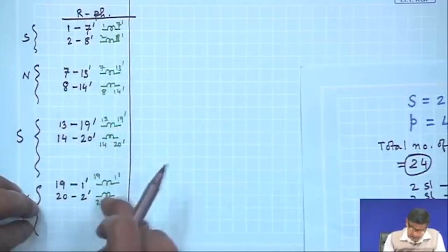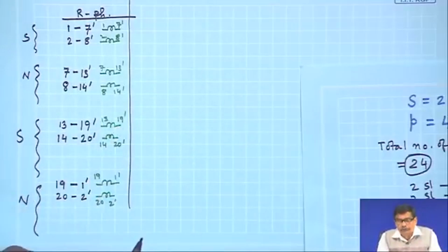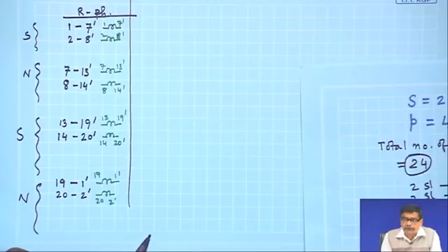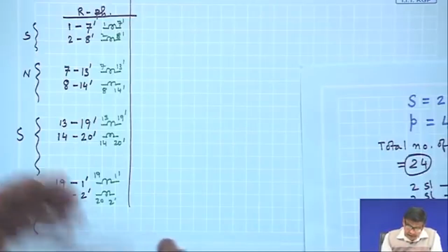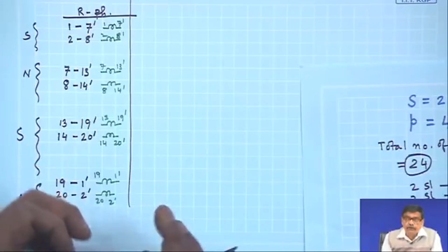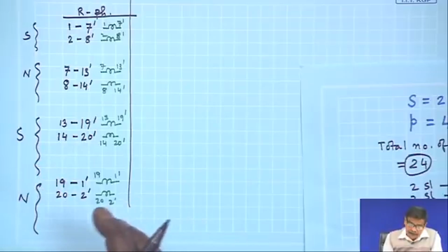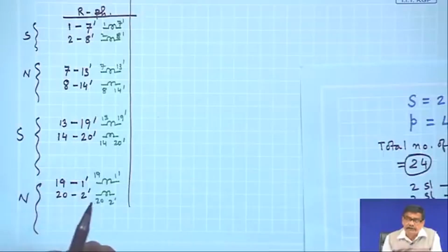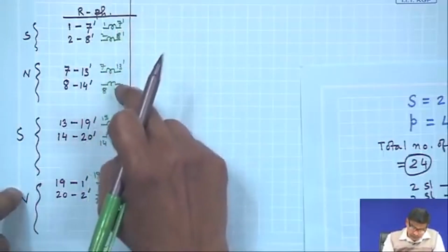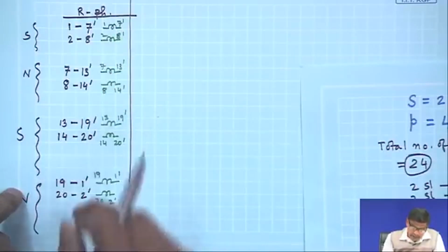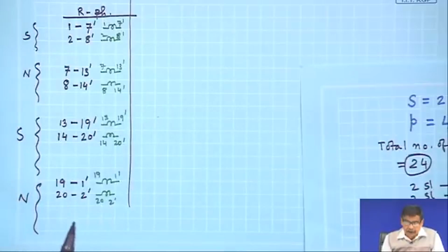These two I will connect in series, get one group, another group, another group, another group. So, if you decide that you will distribute these slots such that under one pole it is equally divided among the phases, that is each phase will occupy 60 degrees, then the number of groups of coils that will be available will be equal to the number of poles.